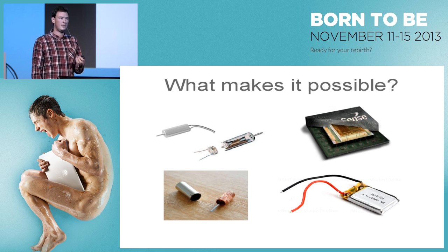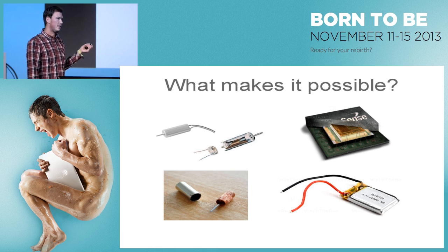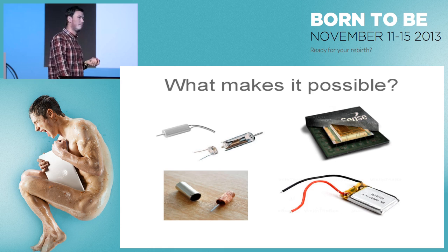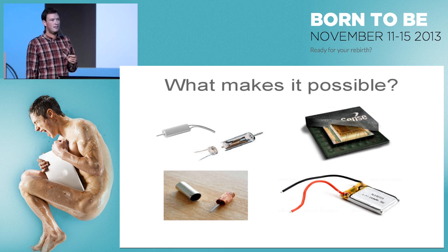So they're very lightweight, and they have a very high RPM. But they're pretty powerful. These motors weigh about 1.7 grams, but they can produce a thrust of about 8-9 grams. So that's pretty good. And also these sensors, the MEMS technology, without it, it wouldn't be possible to make something like this. And the batteries are also very powerful for their weight.